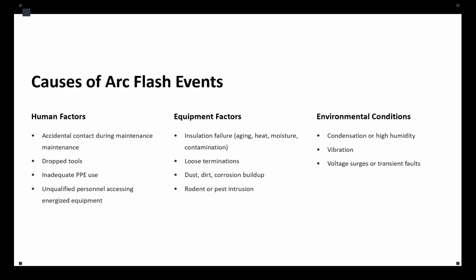Now, another factor is dust, dirt, or corrosion buildup. These are all conductive or semiconductive contaminants, and over time they can form an unintentional bridge between the conductors inside our system. We also have rodent or pest intrusion, which sounds a little awkward and unusual, but is quite common in outdoor or poorly sealed equipment.